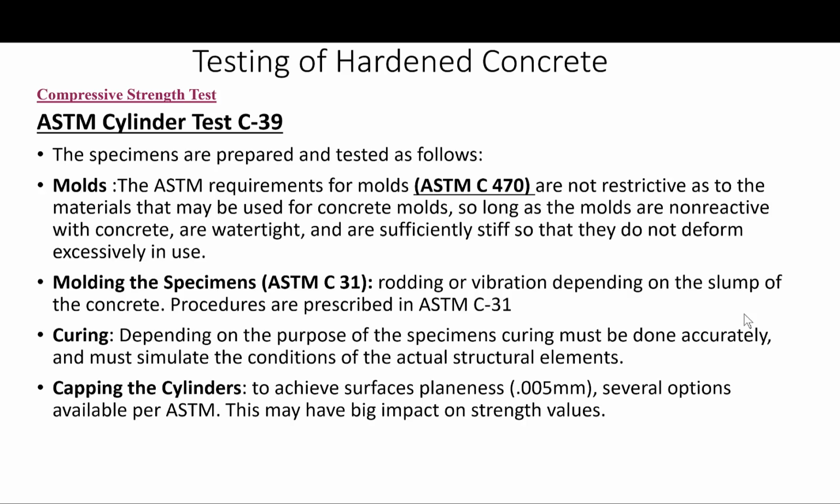Okay, curing. This is important. Cylinders are made primarily for 3 reasons. 1, to check whether the laboratory design mixes achieve the specified design strength, as the basis for acceptance or for quality control. 2nd, to determine when the forms can be safely removed. 3rd, to determine when a structure may be put into service or when the pre-stressed concrete members can be tensioned.